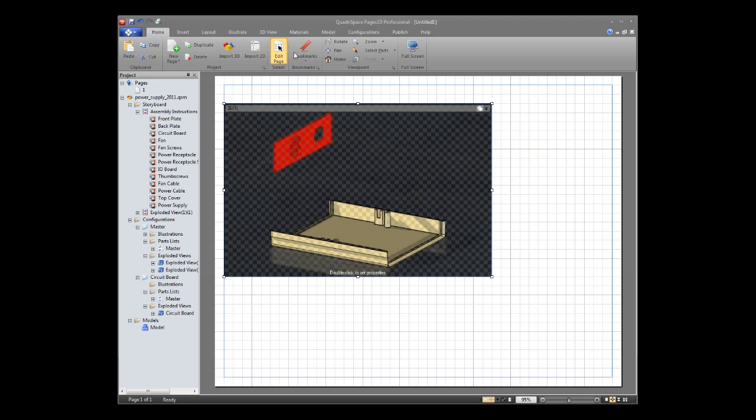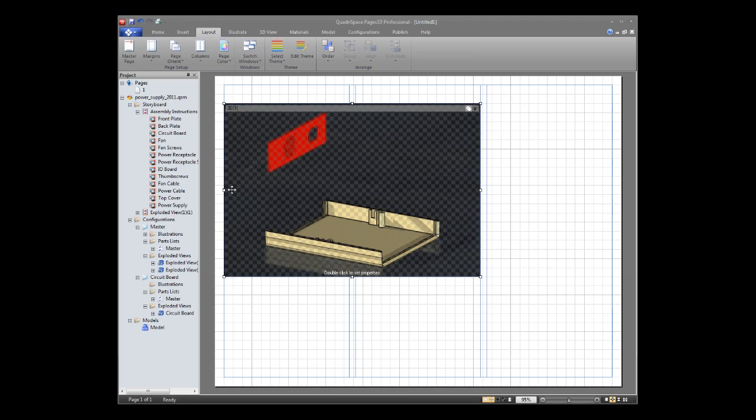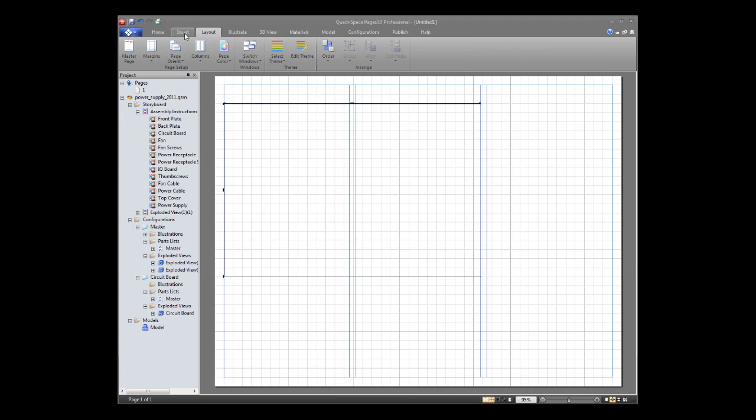We're going to ultimately, let's go to our layout, and I want to put 3 columns here. And so let's go ahead and fit this into these 3 columns. We're going to ultimately put a bill of materials, I believe, over on this side. And we're going to put a description down here with some buttons to move through the description. So what we're really creating here is an assembly instruction using these assembly steps laid out on a page. And we're going to use one single page that will ultimately have next buttons going through those descriptions that you saw and the animations.